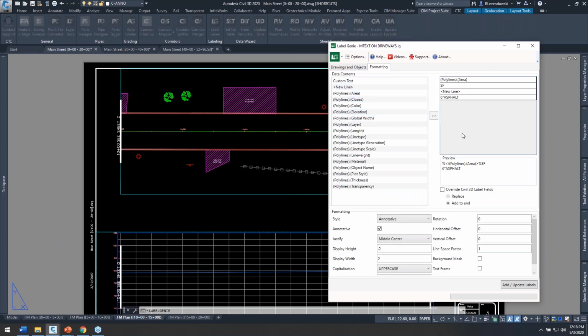some of the data formatting over here. Some of you might be saying, well, I don't put just SF. I put, you know, a period in there, or I put commas in there, or you name it. Anything you can type in a piece of MText, we can put in here. So however you notate your stuff, we can do it here. All we're doing is automating the creation of all this MText. So maybe it's s.f. comma, right? That's the actual formatting we want.